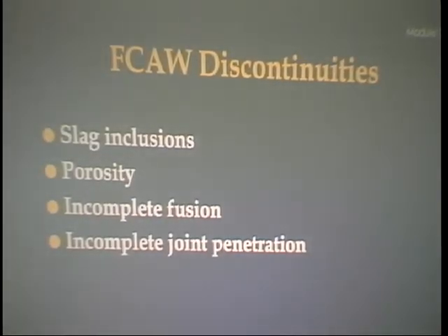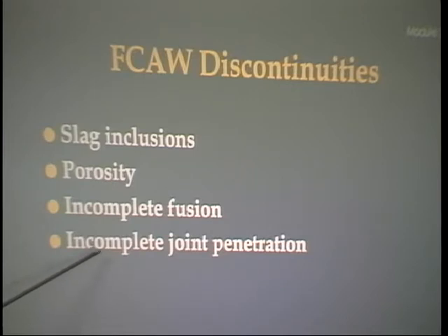Discontinuities. If you don't do a good job cleaning, you can have slag inclusions. Porosity can be a problem. Incomplete fusion can be a problem. You could get overlap on a bead. And if you get overlap, of course, you're going to have lack of fusion. Typically, this isn't such a big problem with Flux-Core because it does produce such a huge amount of heat and depth of penetration. But if you use an improper technique, it could still happen. And then incomplete joint penetrations. Typically, you'll use Flux-Core with a backing strip or a back weld, and that eliminates this problem.